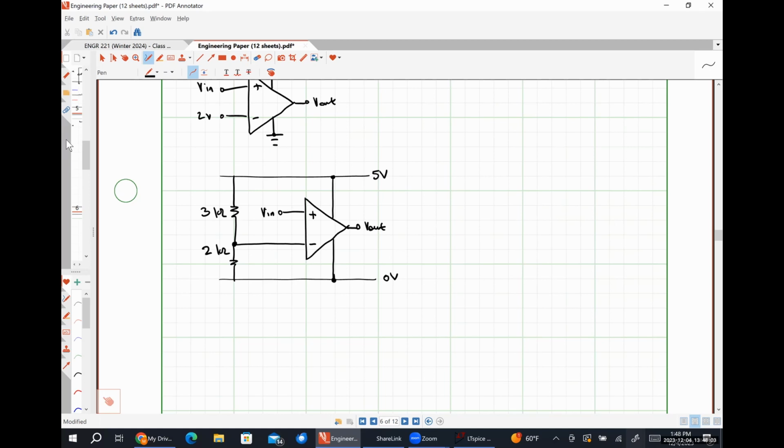Yeah, but I'm trying to think about how we're doing this. So VTH, can I write this down? So I'm going to do KVL around it in this direction. Okay, so negative 2VX. But here's the thing, there's nothing there because it's not part of a closed current carrying circuit.